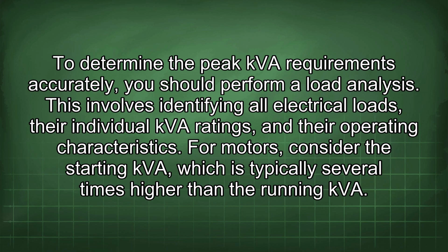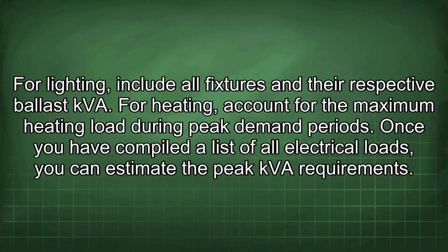For motors, consider the starting KVA, which is typically several times higher than the running KVA. For lighting, include all fixtures and their respective ballast KVA. For heating, account for the maximum heating load during peak demand periods. Once you have compiled a list of all electrical loads, you can estimate the peak KVA requirements.